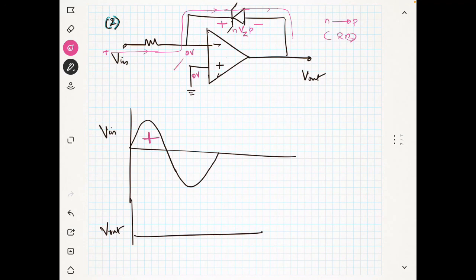And your output, you know, this is again ground point, so I can draw along the Zener diode along here now, and the voltage across this is plus minus Vz. This end, I told you, is grounded, this is virtual ground, and my output is directly connected to the minus, so my output will be minus Vz. So minus Vz will be my output.